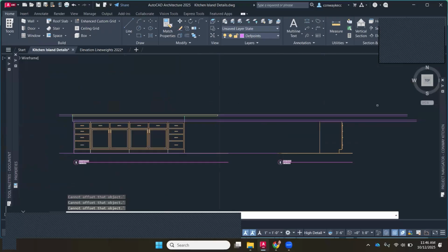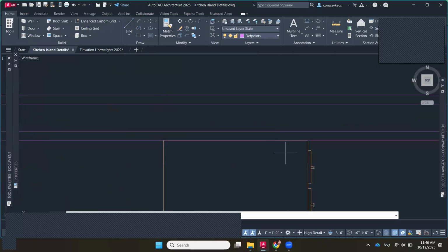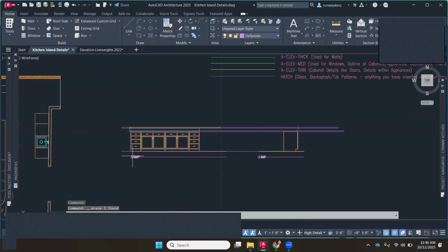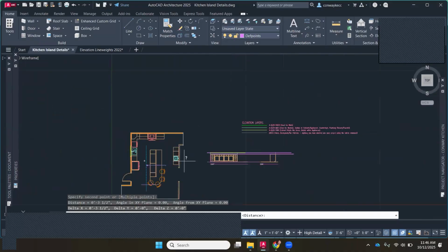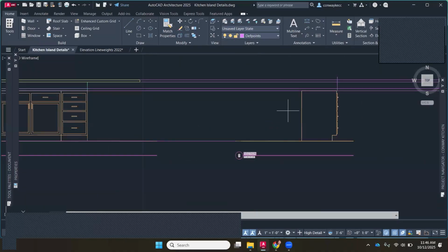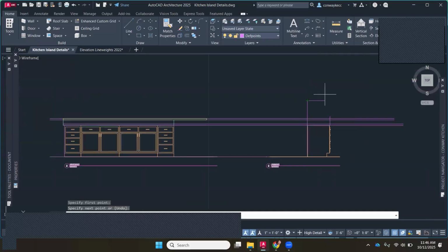So my countertop starts not quite here. So we're going to pop this over to about 1/2 inch because your countertop usually hangs over just a little bit. So it's going to start there. And then we got a couple things going on. We have a tiny little baby wall here in the middle. Let me check what I drew it at. Probably 3.5. Let's see. Yep, 3.5. Because that's kind of the smallest we can do. We'll talk that out in just a minute. So we go here, escape, 3.5 inches, go to the left. That's going to be my little baby wall in there.